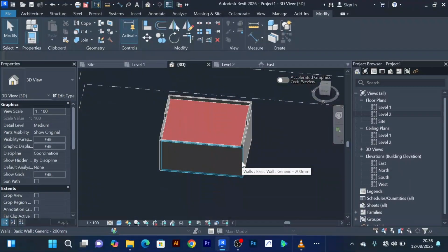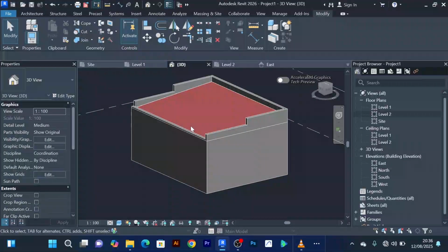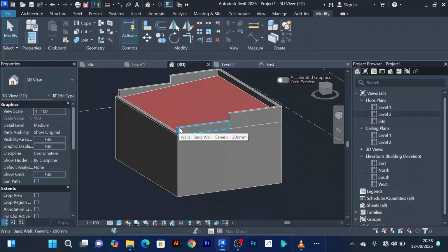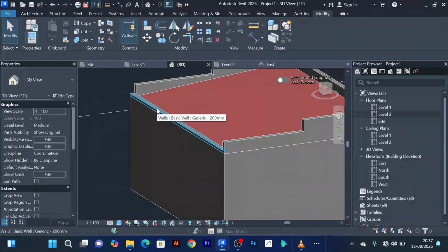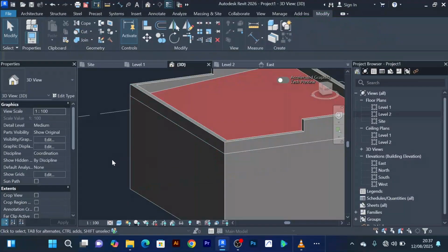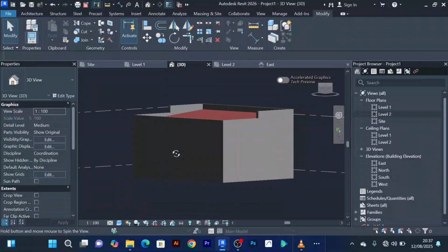And with the modern way of designing houses, people now change this lean-to roof style. They make it a hidden roof. So making it a hidden roof is just a matter of extending these parapet walls to hide the roof all over. For example, here you realize someone will increase this to, let's say, 500, just like that. And if you look at the roof, you can't see anything.